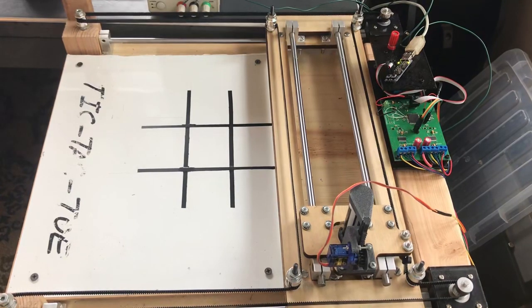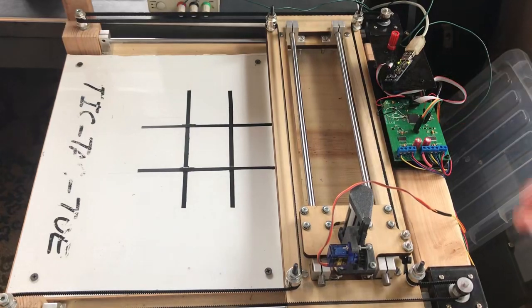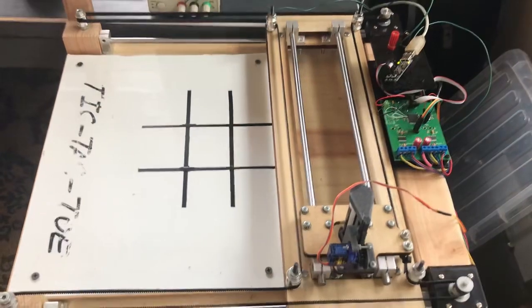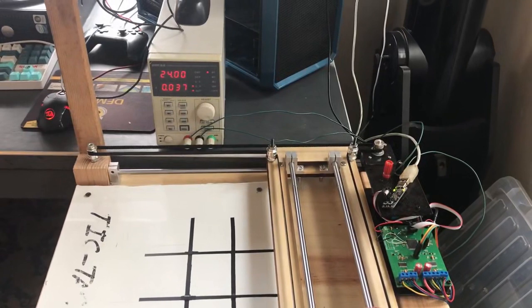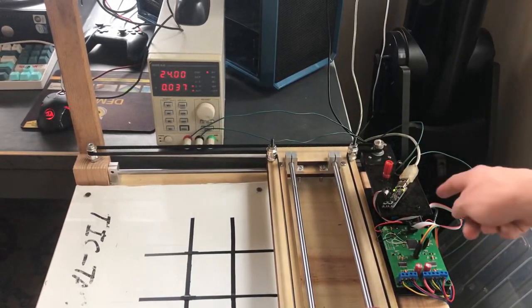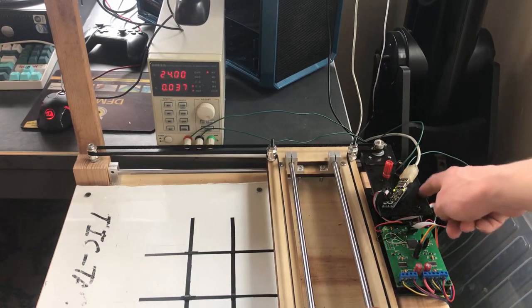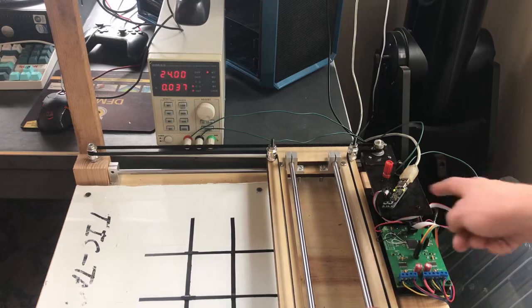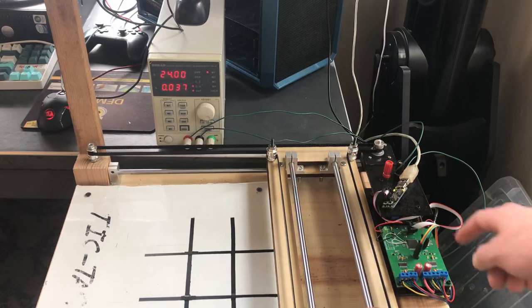The last components, moving further up, there is a power supply that is set to take 24 volts. Let me change camera angle real quick. So 24 volts directly in from the power supply. There's a soldered Y connector, you can't see it, that directs the 24 volts directly into the motor controller side of the board. And there is an internal DC-DC converter in here that steps the 24 volts down to 5 volts for the microcontroller.